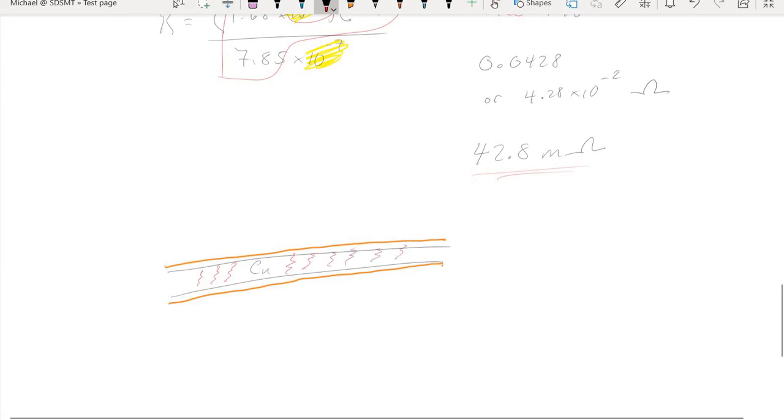it needs to dissipate that heat, and where is it going to dissipate it through? Well, it's going to dissipate it through that protective sheathing, and that sheathing is usually made of some kind of polymer composite or a plastic, and that plastic could do one of two things. It could melt. And if the plastic melts, then you've got an exposed section of wire, which can then short circuit, could cause a spark. Another thing that could happen is that as that plastic sheathing melts, it could catch fire. And that fire could then spread to some other area.